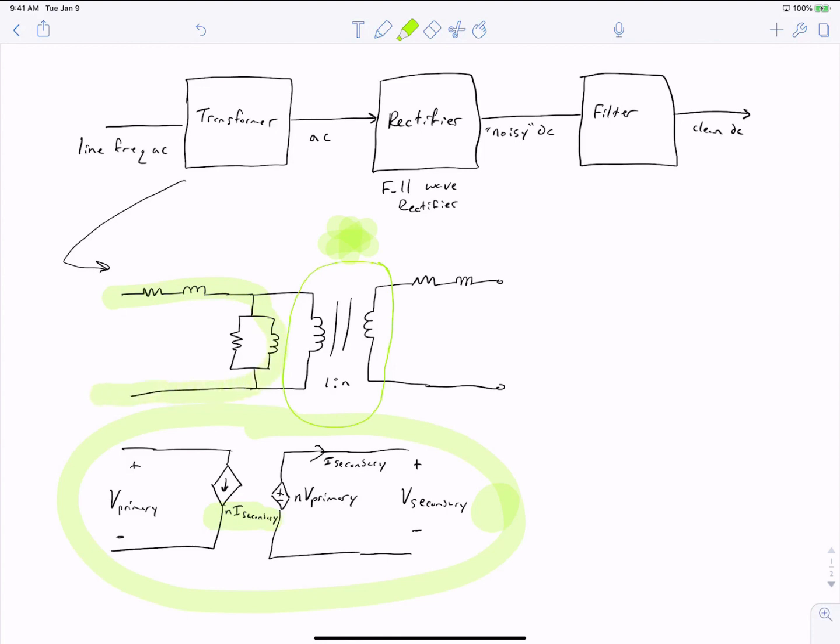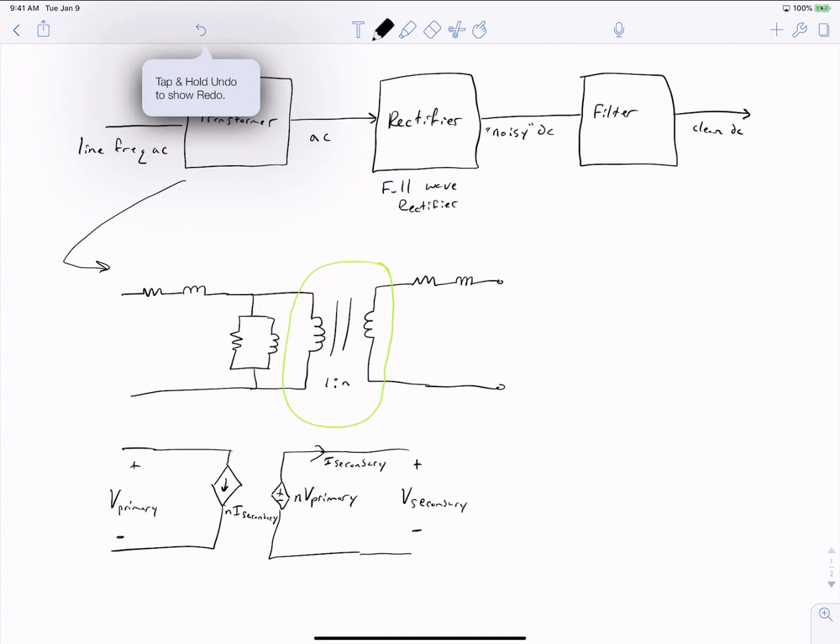So in order to capture that information, we must actually add all of the elements that we have over here to our equivalent circuit. We would then start to add our stator winding resistance, our leakage inductance, our network over here of the resistance and inductance, and so on and so forth.